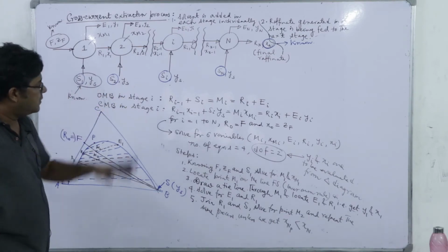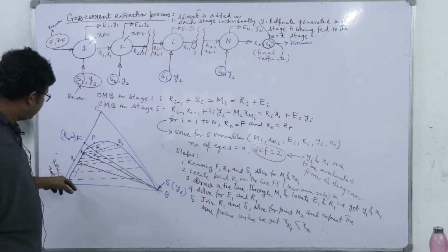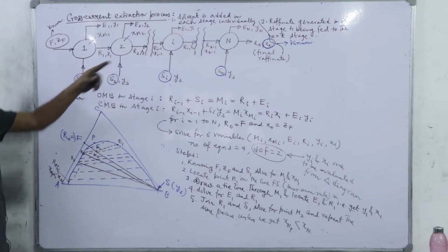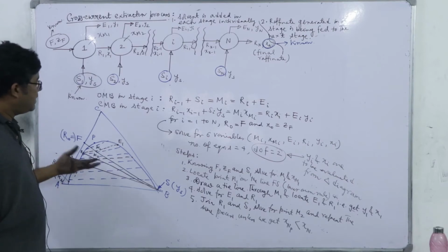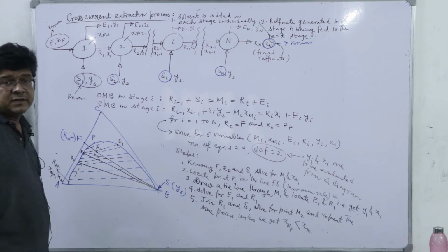So, same. So, you go on repeating that until you get a point RNP where it is less than the target raffinate concentration. So, there we stop and finally, NP will be my number of stages required.